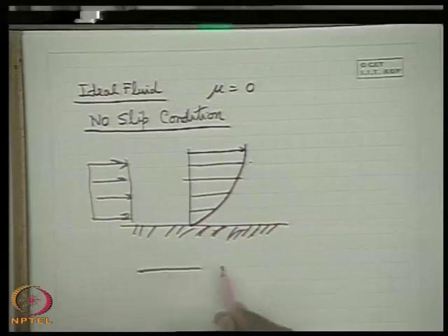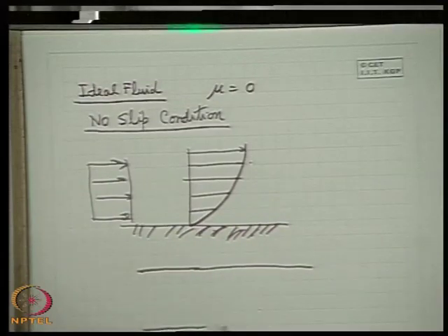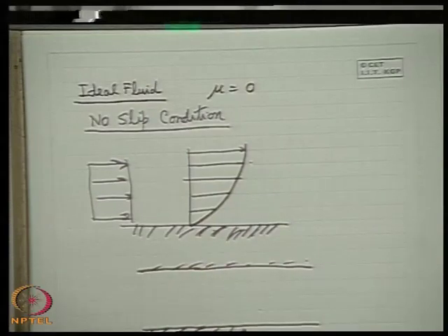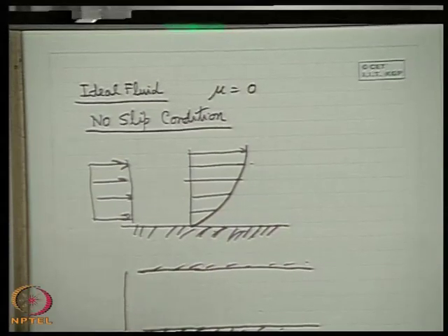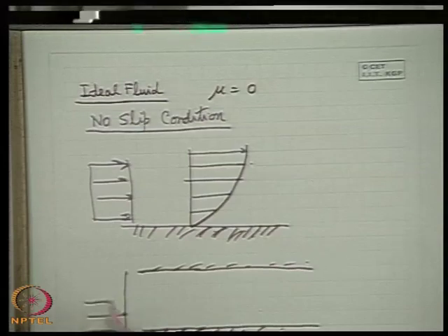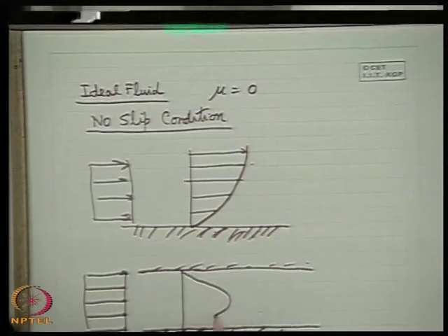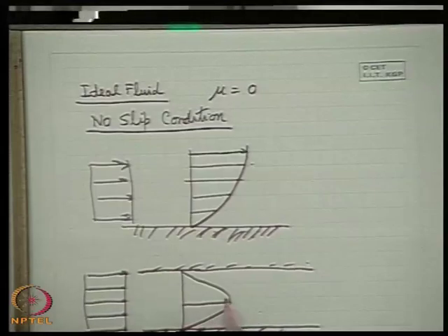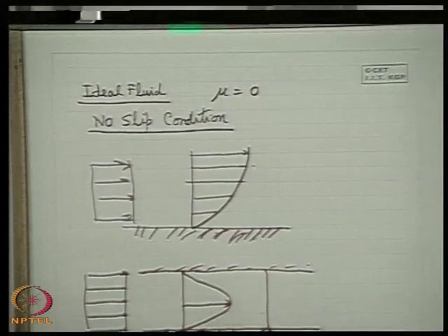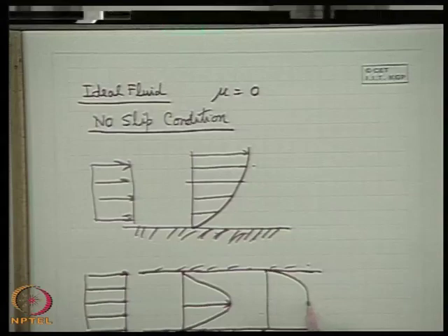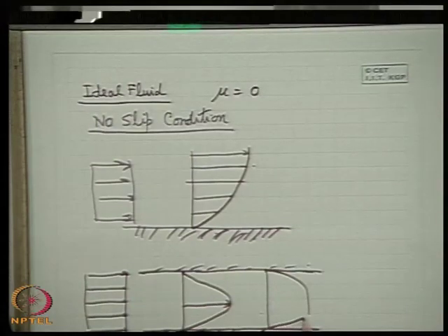Similarly, in a pipe flow, I just give you the picture which will be taught in detail afterwards. In the case of flow of fluid through a pipe, if the flow approaches first with a very high, uniform velocity, whenever it comes in contact with the solid at any section, the fluid velocity will be like this. There will be a distribution. A maximum velocity usually occurs at the center. So the velocity at the solid surface will be 0. Depending upon the level of flow velocity, the variation will vary. Sometimes we get this type of D-shaped variation, a little uniform at the center.